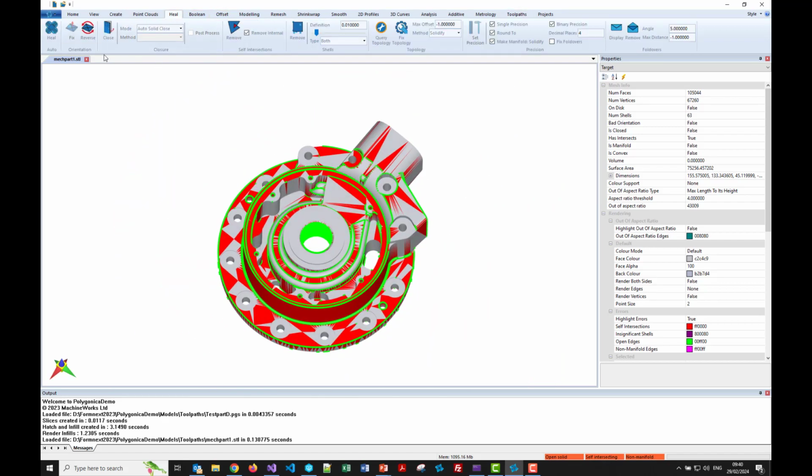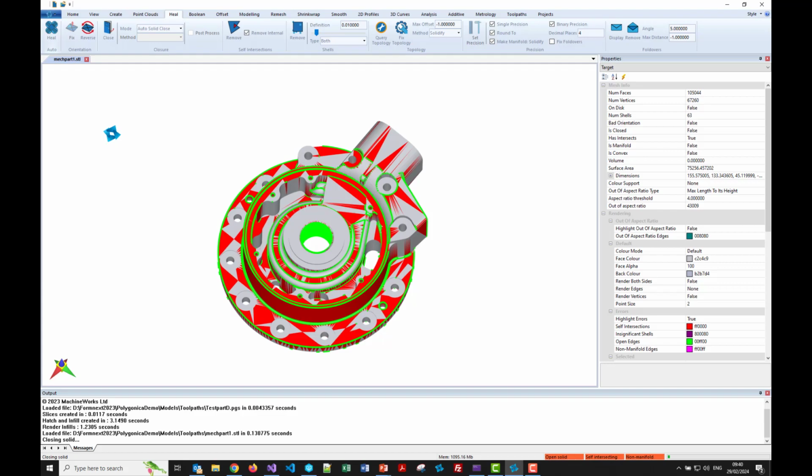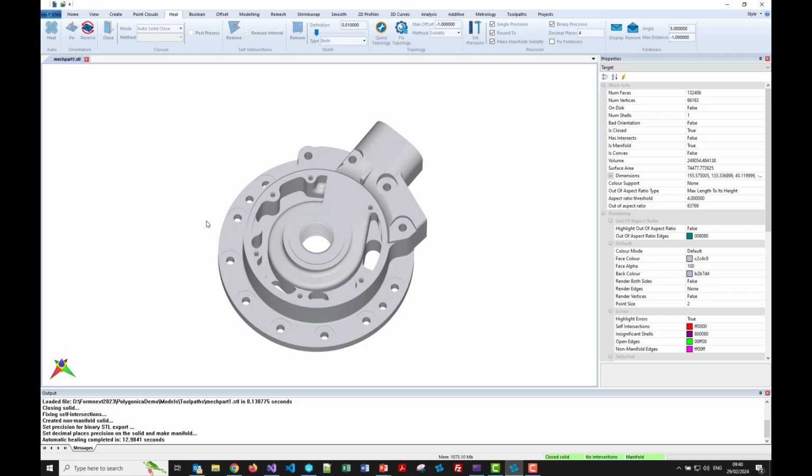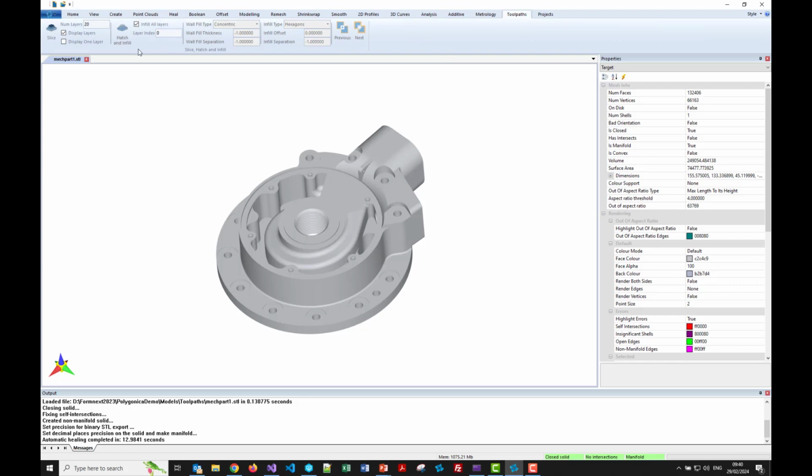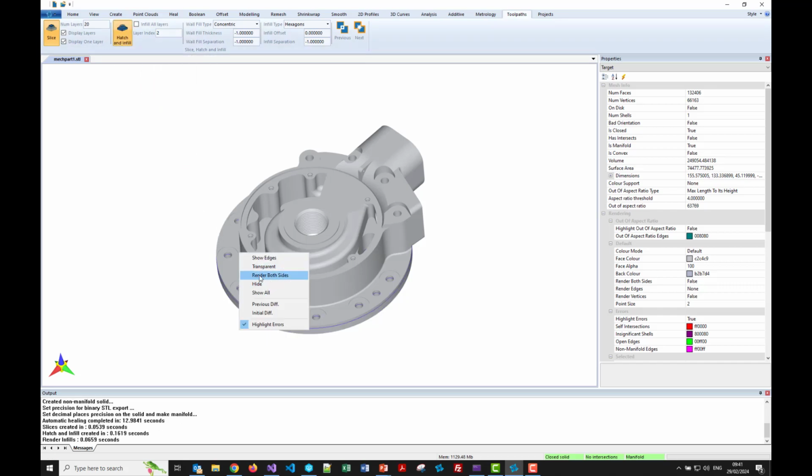But Polygonica is justifiably renowned for its automatic mesh healing. By now it's been tested against pretty much everything, and certainly in my experience, it always wins when those tests are done. This is a complex thing to resolve, and it's done that in 12 seconds. So now we have a nice watertight mesh that's self-intersection free and manifold. I'm just going to create 20 layers there, and in this case I'm just interested in layer number 2, because it's quite an interesting layer to demo.